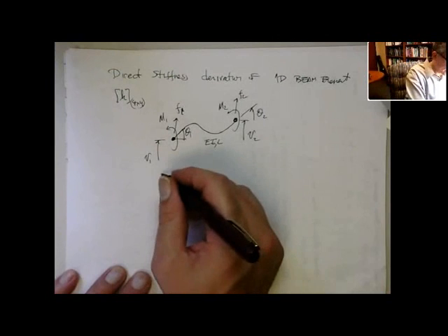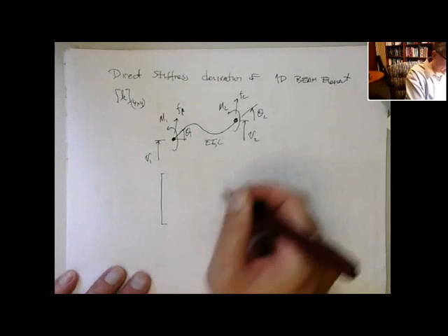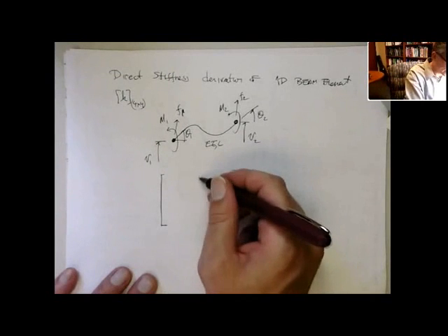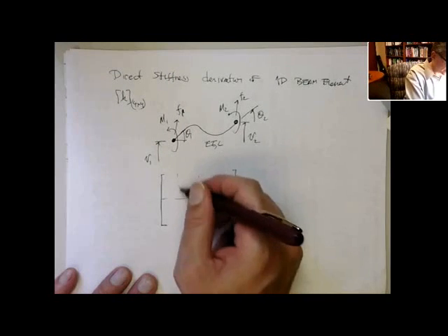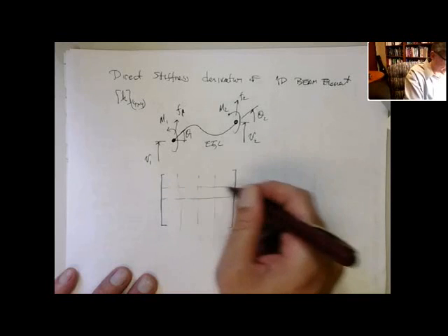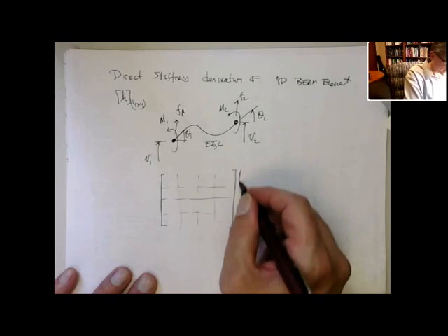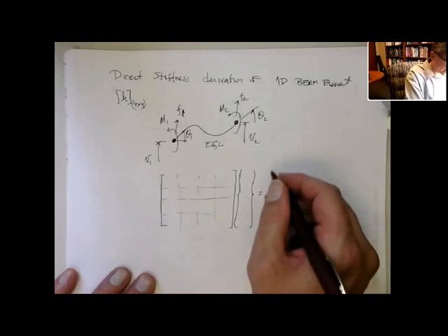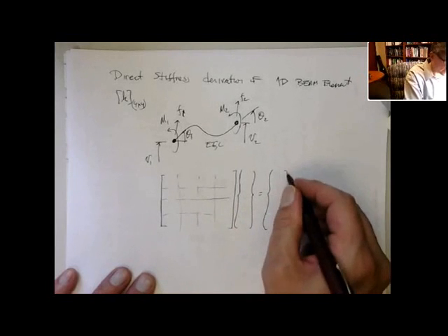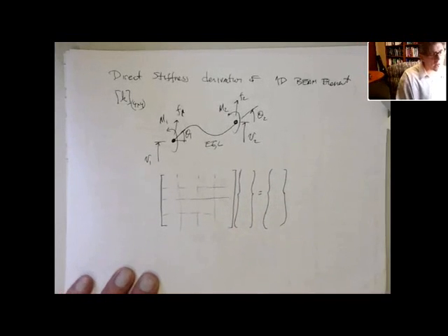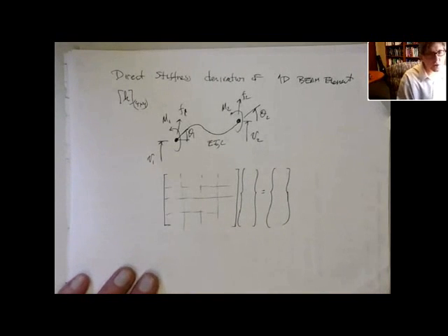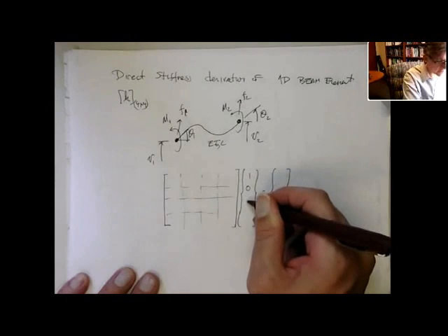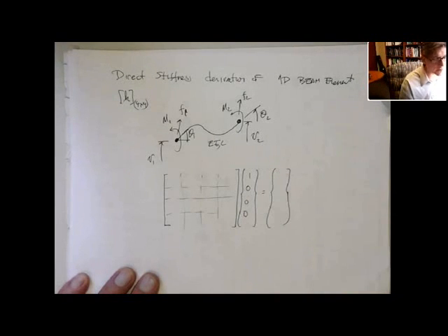If you think of a stiffness matrix like this, that's unknown, right? And in this case, this is our 4x4 stiffness matrix. It gets multiplied by a displacement vector, and that equals a force vector. If we assume a displacement, so we're going to assume displacements, and so for example, let's say we assume the following displacement,